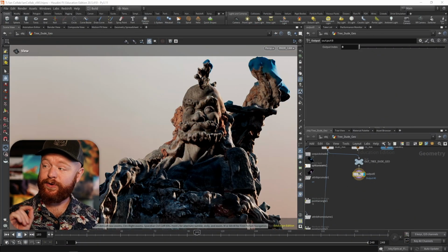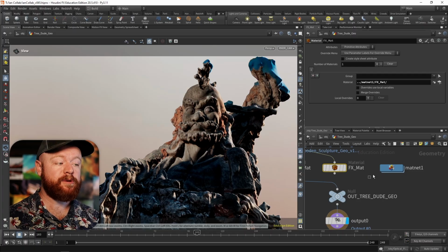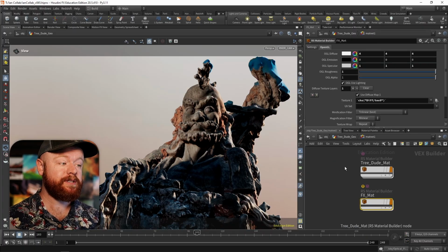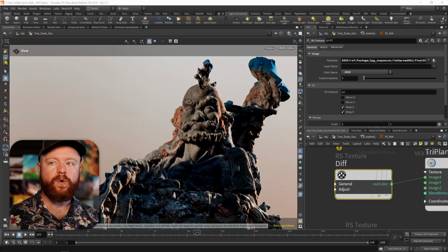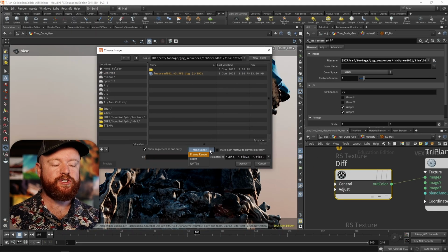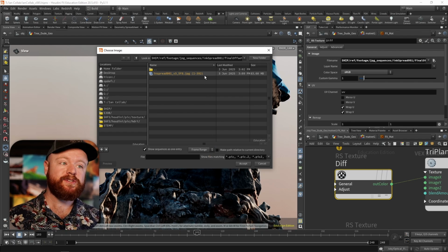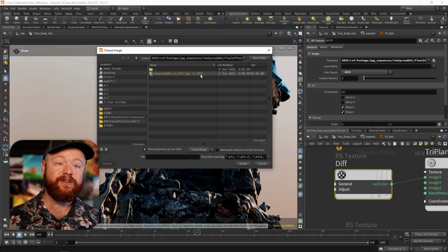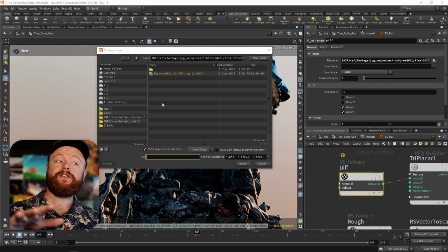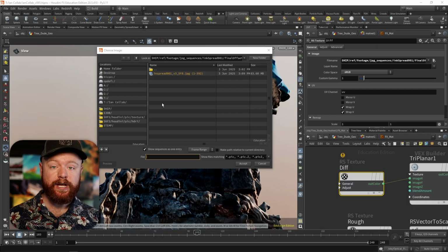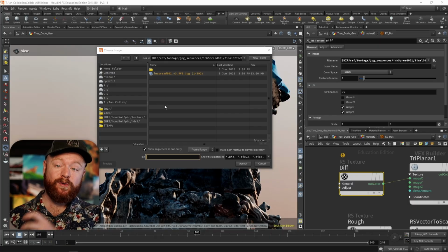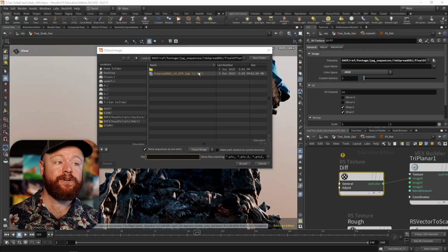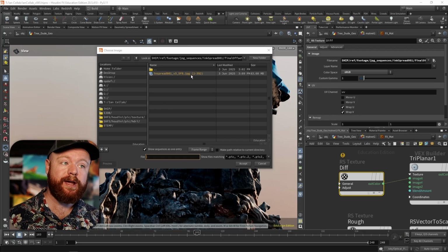Now in Houdini, we are ready to use our triplanar projection with that TIFF sequence to make it all happen. So to load that in, we just browse for those images and then make sure that you have this frame range turned on. You should see it go from 1 to 400 or however many frames you may have. And if the range is not starting at 1, then double check the naming of your files. In DaVinci, there's an option to have it start at 1. So just double check that if you're not seeing the right range appear right here.